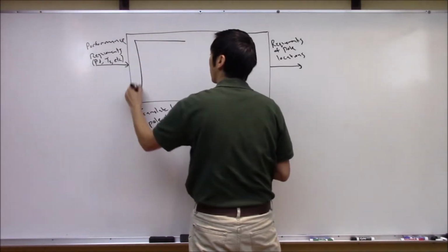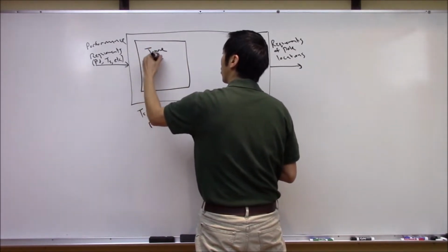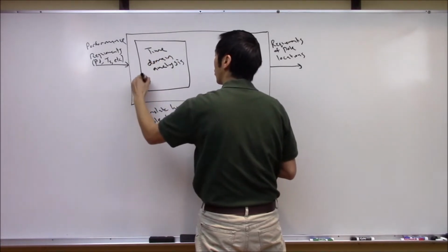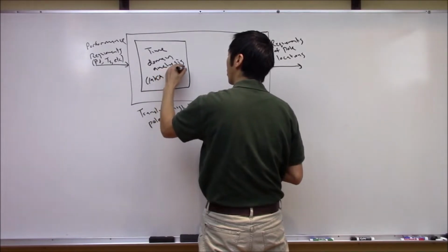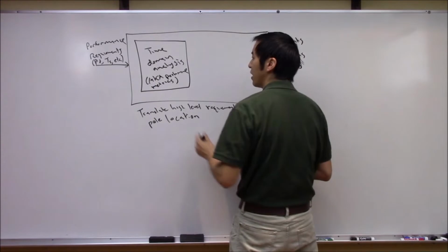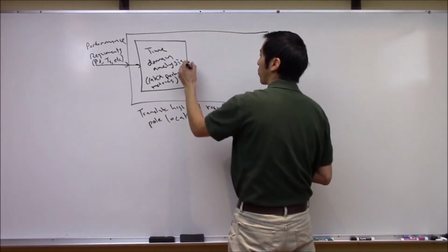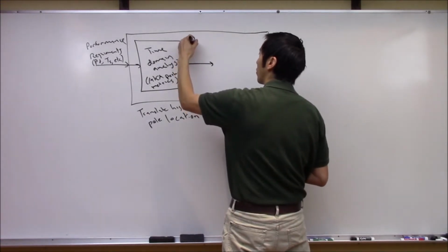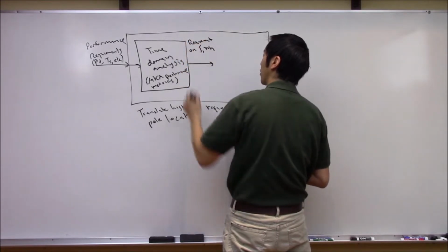This was also known as performance metrics. Basically what that did is it allowed us to translate between percent overshoot, settling time, those performance requirements, and those we saw place some kind of restriction or requirement on zeta and omega n, right?